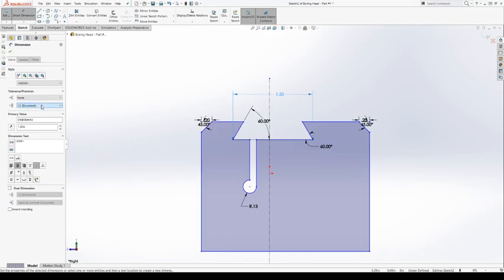One of the best things that we can do here, though, and one of the things that will save us time on the back end when we make prints, is using our tolerance and positioning attributes. So right now, this is to a 2 decimal place tolerance. But if we look at our print, right, this guy is going to 2 decimal places plus 1/2 minus 0. So in my mind, anytime I see a dimension like that, since the tolerance is going to 4 decimal places, I would expect the original dimension to go to 4 decimal places. So I'm going to change that. So now we are out to 4 decimal places, right?